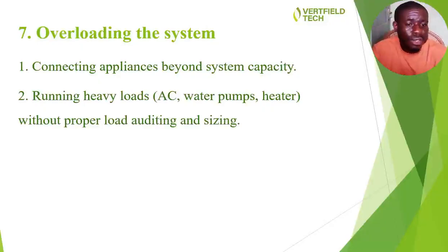Running heavy loads, your AC, your water pump, your heaters, without proper auditing or sizing. Yes. Not all inverters are suitable to power these heavy loads. Please, whenever you know you are going to be running heavy loads on your inverter system, ensure that it is a transformer based inverter that you'll be using, because these are high current drawing appliances: your AC, water pumps, heaters, freezers.